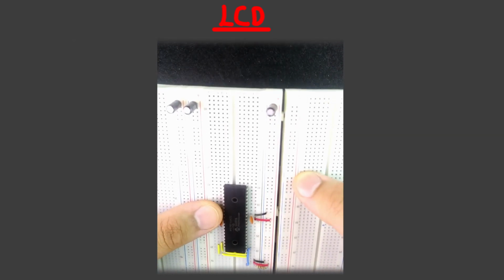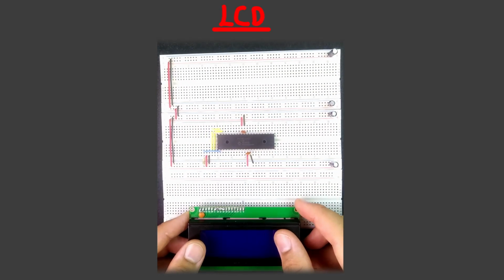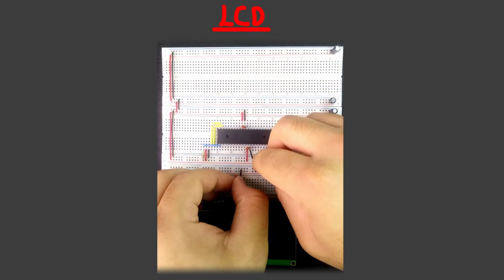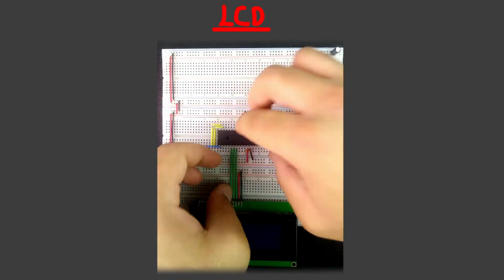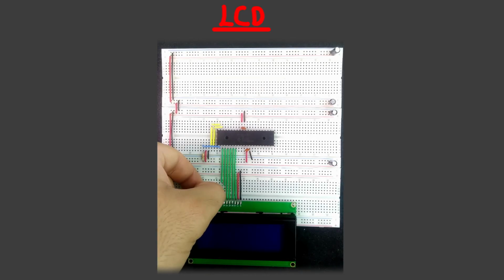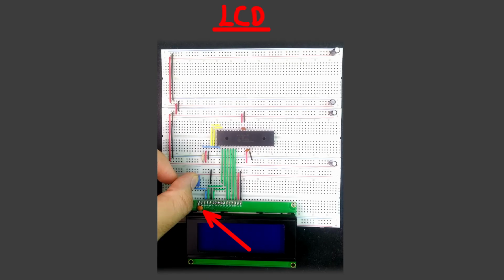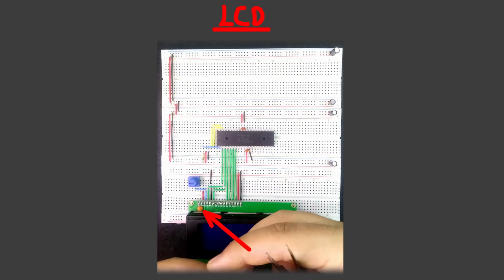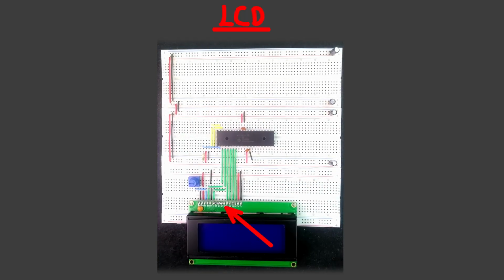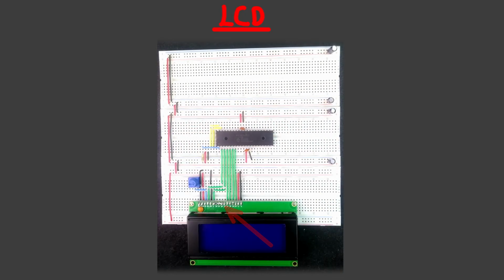I'll add another breadboard to my circuit, and I'll be using this setup sideways from now on. I'll speed up my connections for you. You don't need to go through this much effort, of course. I just want it to look clean since I'll be using it in future videos as well. I also directly soldered the optional decoupling capacitor on the LCD itself to not have to connect it on the breadboard, and the lower 4 data pins together to the E pin to not leave them floating.